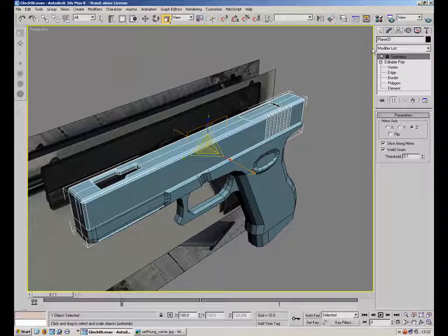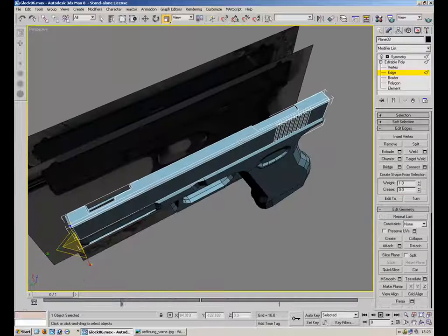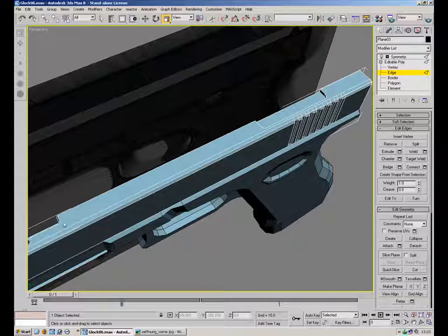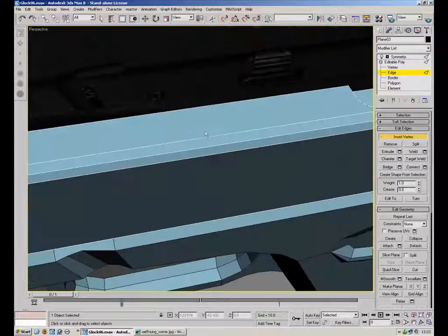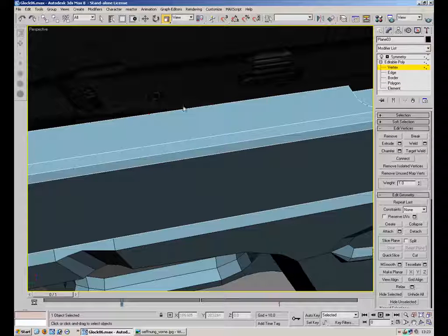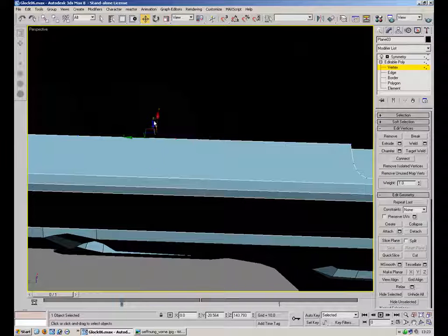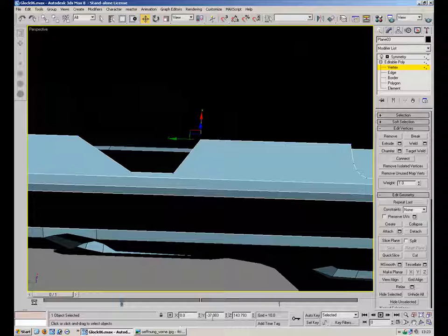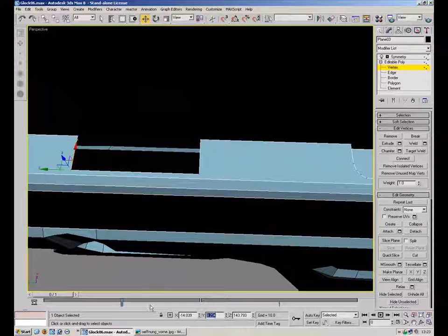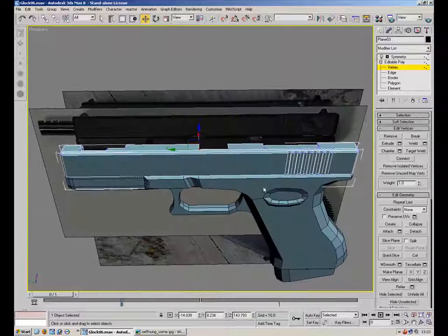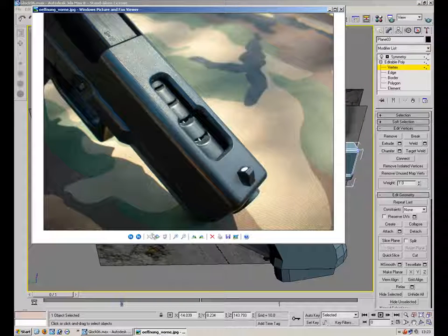I think the best way to do it is exactly the same as I did for these two, sort of indents. I'm just going to insert. Once I've got my vertex inserted, I'm going to get them into the right positions. So I need to take the Y position from here, transfer it to here, and the Y position from this little guy and put him over here. Right, I then want to try and get this into the correct position.